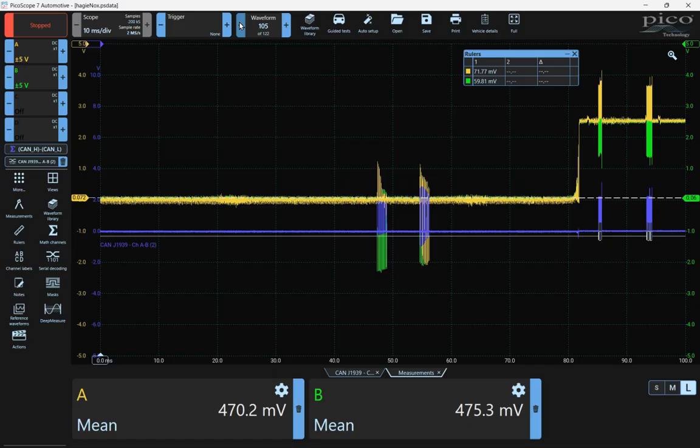It's close to aftertreatment components, and it was able to poke its way into the CAN high or CAN low. It doesn't really matter which we shorted. In this case, it was probably CAN high, because of the terminating resistors, as I could explain later.